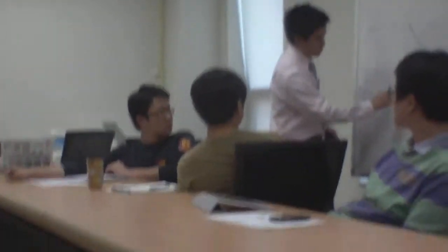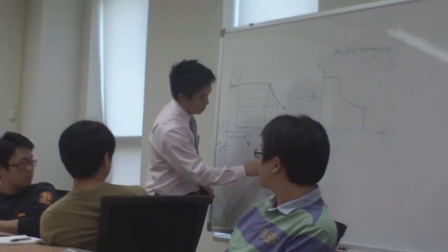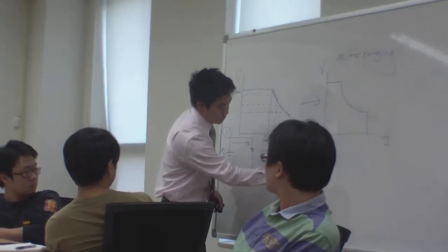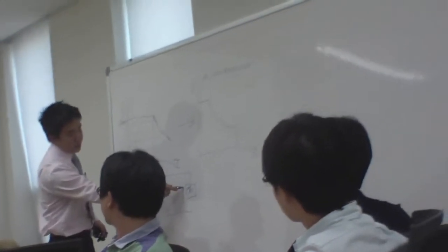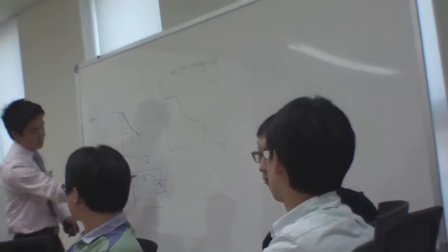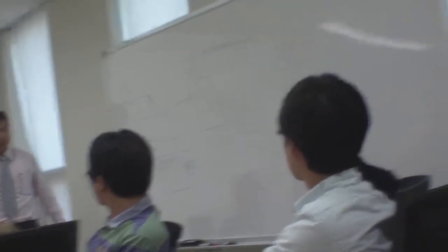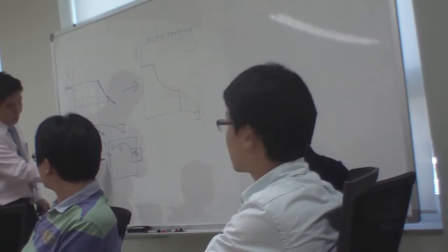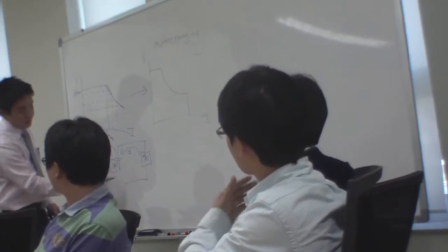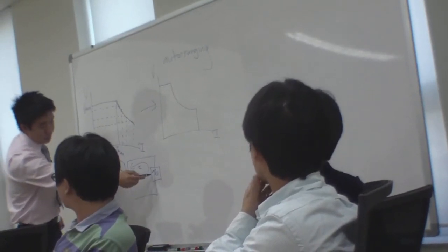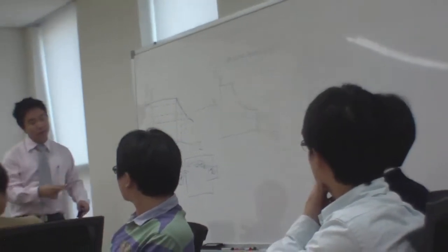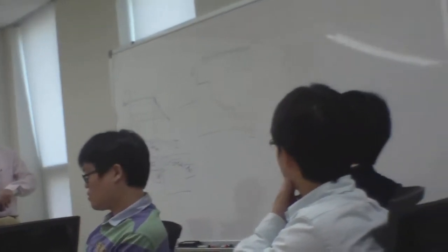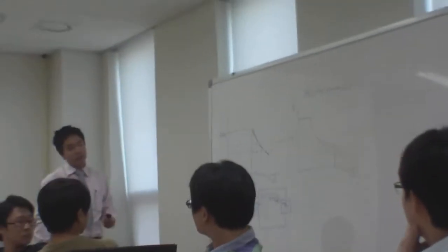Feature number 2 actually allows you to connect your power supply to some sort of active device. Let's say we call it A&D, active device. And you can actually pump current back into the power supply. So let's say you want to sink a constant 1 amp. You set 1 amp here, and this will sink 1 amp and pull 1 amp from this active device. So it allows you to pull current into the power supply as well, as opposed to just sourcing. That's one of the additional capabilities of these modules.